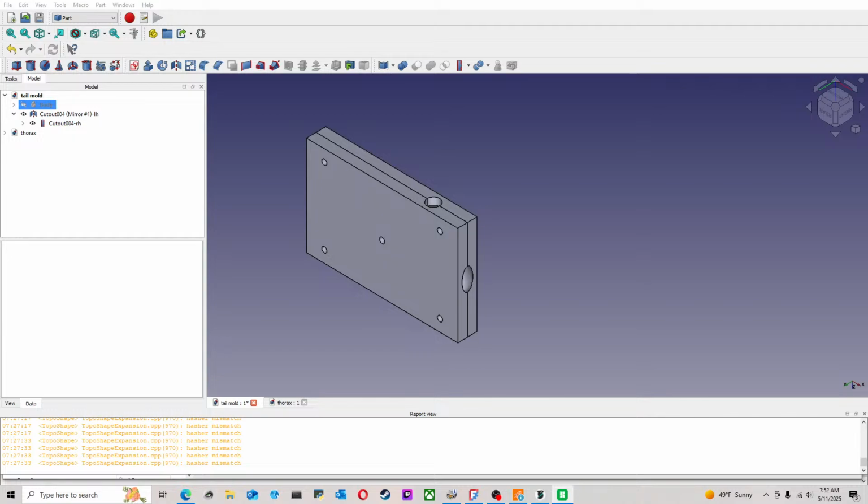Generic polycarbonate. 2mm. I want 5 wall loops. 2mm top and bottom shell with a honeycomb 10% infill, and we will go ahead and slice and about 4-hour print there, slice and print. That one is a doozy.